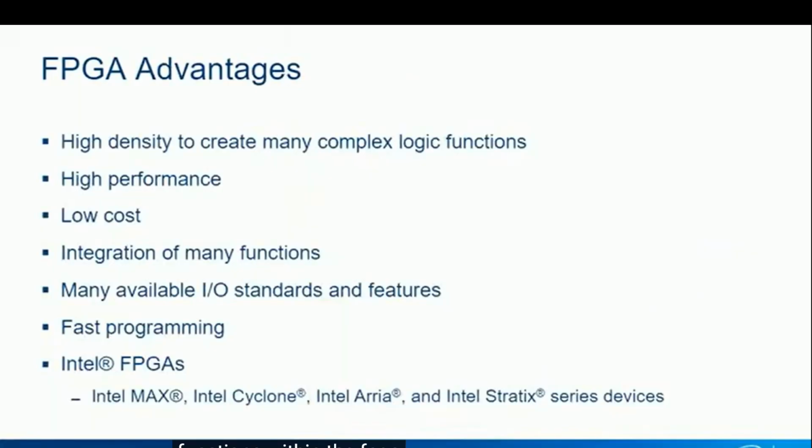With the features described, it's easy to see how FPGAs provide many advantages to the system designer. They include a lot of user logic in a high-density package to enable the creation of all kinds of logic functions, from the simple to the very complex. FPGAs are high-performance devices. Older programmable logic devices were not often used as replacements for ASICs or dedicated logic chips because they could not achieve the clock speeds of those dedicated devices. However, modern FPGAs provide the performance needed for many high-speed applications, making them an affordable solution for many different types of system designs.